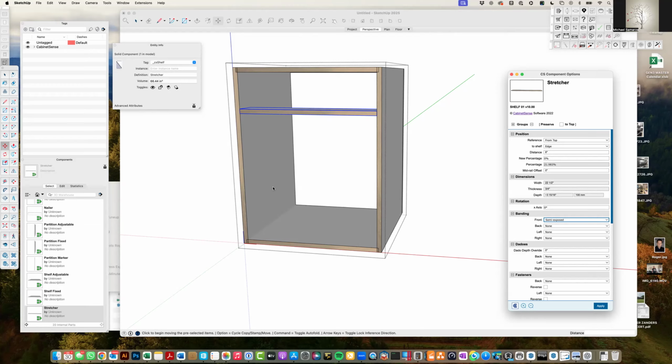So I have 0 width stretchers, but I also have stretchers that are full width, but they're still not seen. We'll hide them, and they still do the same job. You just hide them from your cut list. And then how do you fasten this into the cabinet? Is that just stapled in, or do you do something else? That would be staples, right, Josh? Yeah, either staples or screws.